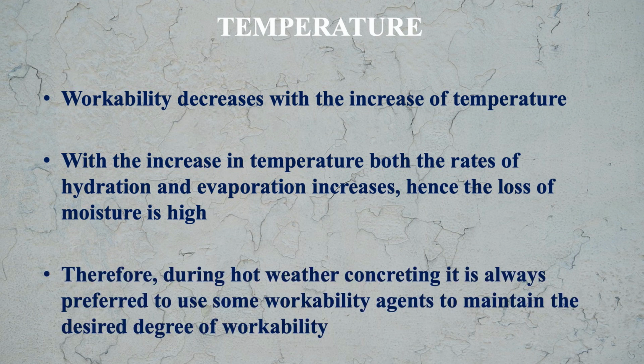Therefore, during hot weather concreting, it is always preferred to use some workability agents like admixtures to maintain the desired degree of workability. So this is necessary that if you are doing the concreting in hot weather, we have to go for some admixtures to add in the concrete so that the desired degree of workability is maintained. And admixtures we will learn in another module.